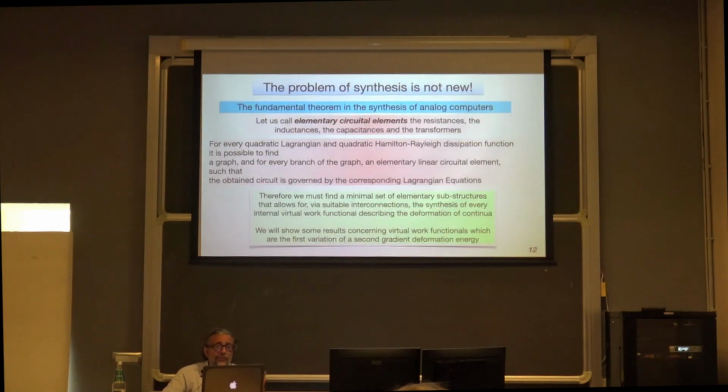So the fundamental theorem in the synthesis of analog computers is based on a definition. We call elementary circuital elements the resistances, the inductances, the capacitances, and the transformers. Why? Because for every quadratic Lagrangian and quadratic Hamilton-Rayleigh dissipation function, it is possible to find a graph, and for every branch of the graph, an elementary linear circuital element, such that the obtained circuit is governed by the corresponding Lagrangian equations.